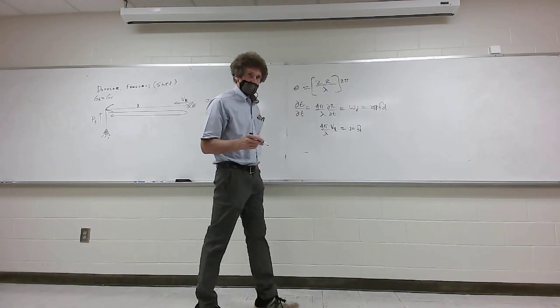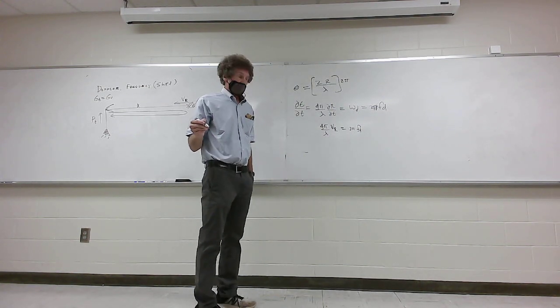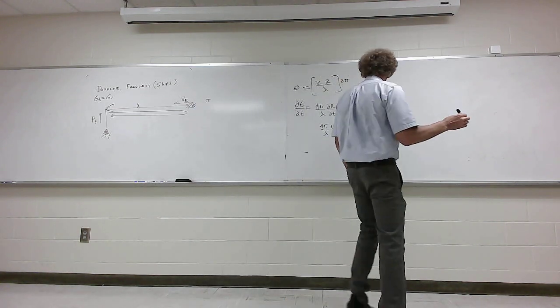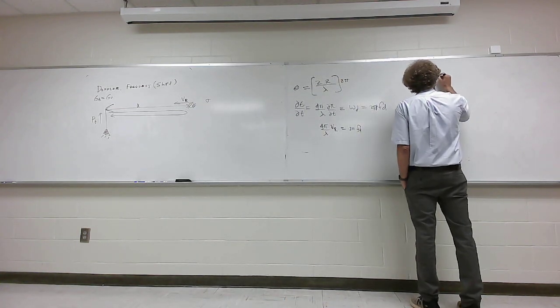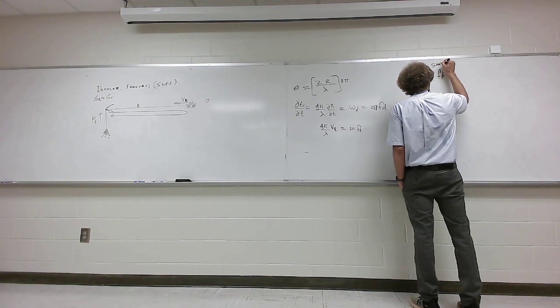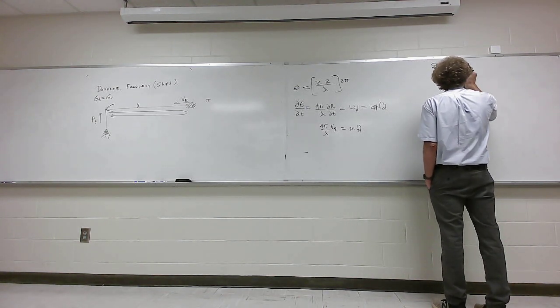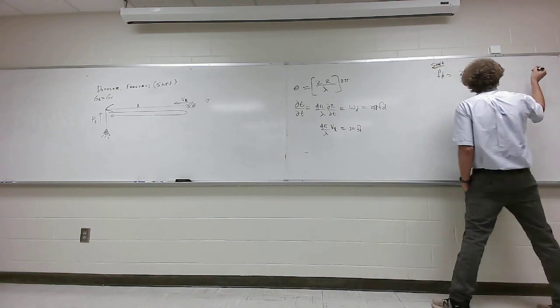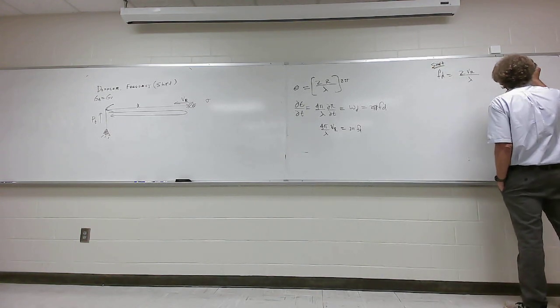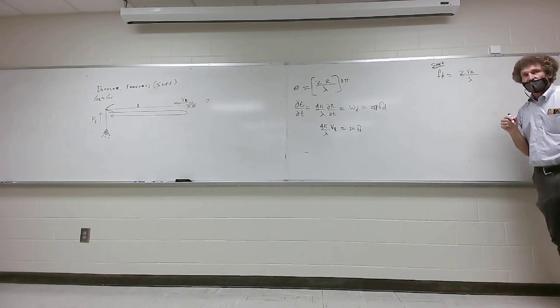And you can see what I'm going to do is cancel those 2 pi's, right? And so now I get the Doppler shift, the actual Doppler frequency shift, which is equal to 2 VR over lambda. And lambda is C over the actual carrier frequency.